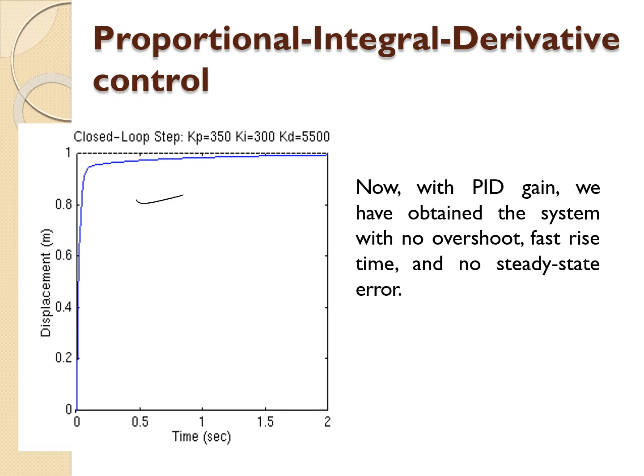So I think it's around here, right? So there is no overshoot in here, and the process, the control variable has reached its set point successfully. So there is no steady state error in here.